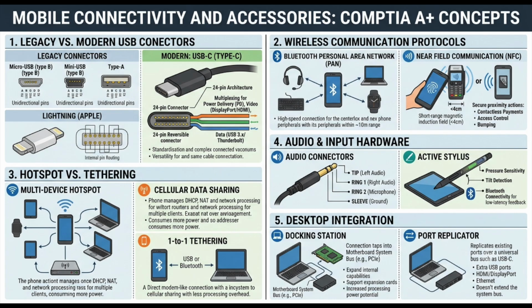And at the exact same microsecond, other pins are operating as dedicated lanes for DisplayPort or HDMI video signals. Pushing like 4K video to a monitor? Exactly, pushing 4K resolution to an external monitor. And simultaneously, the remaining pins are operating under the Thunderbolt protocol to transfer massive data files. It entirely replaces those older USB 2.0 limitations because the architecture is multiplexing power, heavy data, and ultra-high-definition video simultaneously.